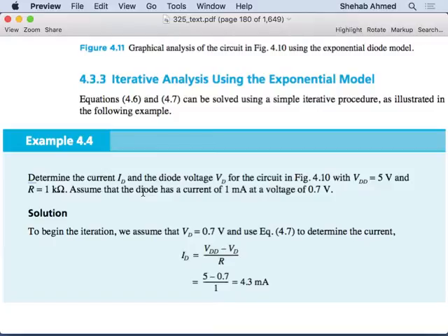You guess based on your best judgment. But best judgment is engineering sense. So you know, based on our discussion, does the voltage across the diode change much when the diode is conducting? No. So what is a good voltage to use? 0.7. Exactly. Right? And you go to your characteristic of the diode, at 0.7 you will typically find a current, let's say ID of 1 milliamp. For this specific diode, they assumed, take diode current as 1 milliamp at 0.7 volts. And then you will iterate.